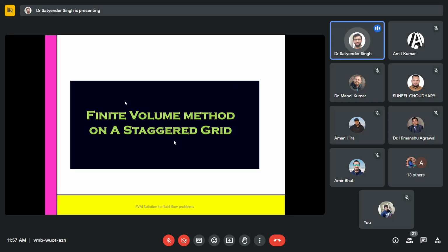The problem that arises: I told you earlier about one grid structure, the computational grid structure, where we divide the computational domain using horizontal and vertical lines and create orthogonal grids, where each grid I was also representing with control volumes to give you the thermodynamic understanding of the problem of the fluid flow and the various physics associated with it.